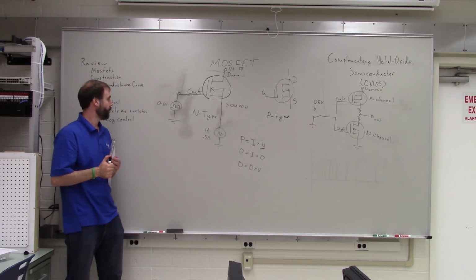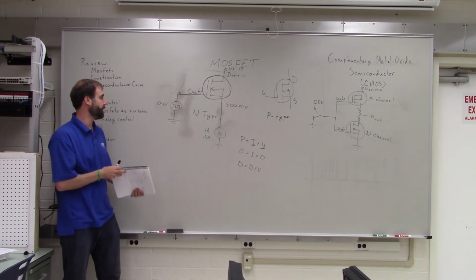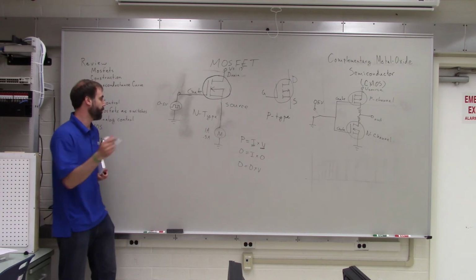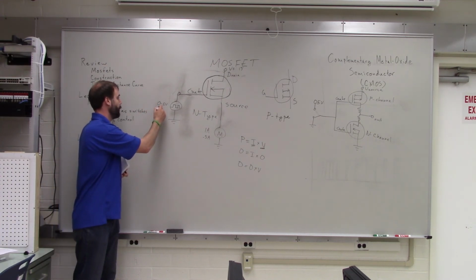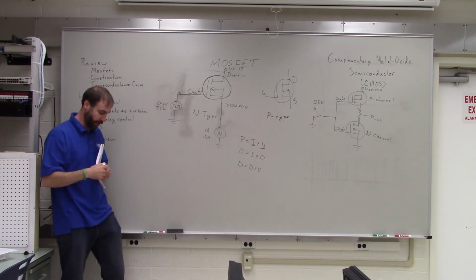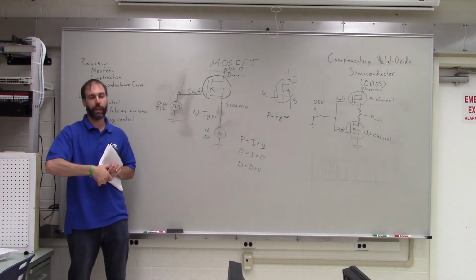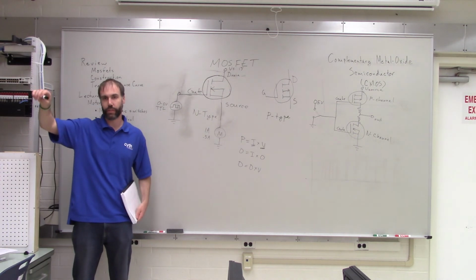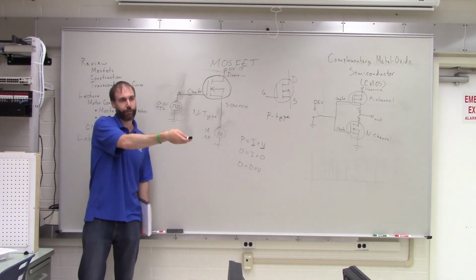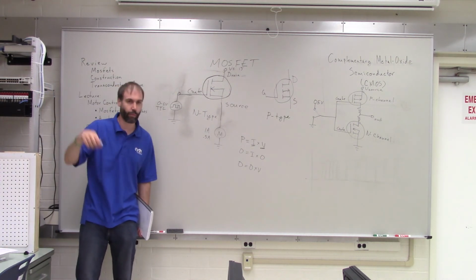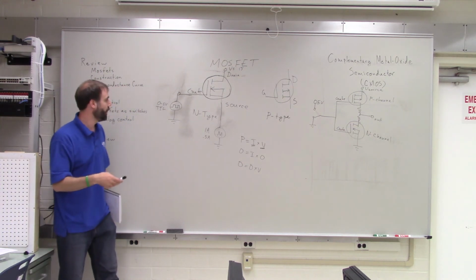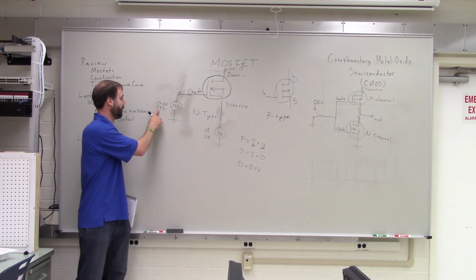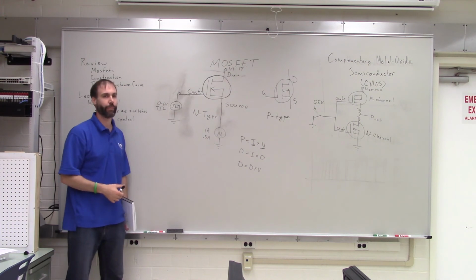When you do this, the easiest thing to do is to use the TTL output from your function generator. So this is the plug that's on the left-hand side of the function generator. So you're going to take your BNC cable and plug it into the left side of the function generator rather than the right where you normally plug it in. Okay? That'll set it to be automatically 0 to 5 volt output.